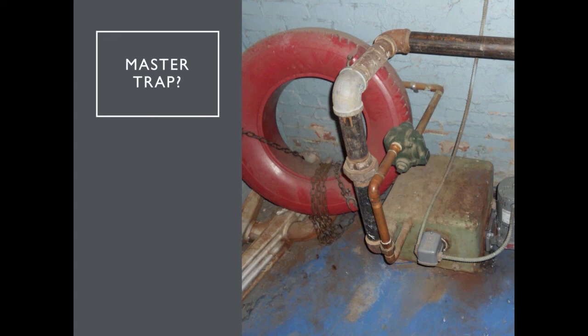Okay, and we have a question here from Ed, and he says, can boilers with burn marks still be used after the problem is fixed? Oh yeah, definitely. I would definitely try to clean it up or paint it or something like that, so you know if it ever happens again. A lot of times on those ones that had the burn marks, we would disassemble the whole thing, clean it all out, and reassemble it. And then I would like to try to paint that jacket so that the next time I'm out there, if I see it's discolored again, I know that there's a problem.